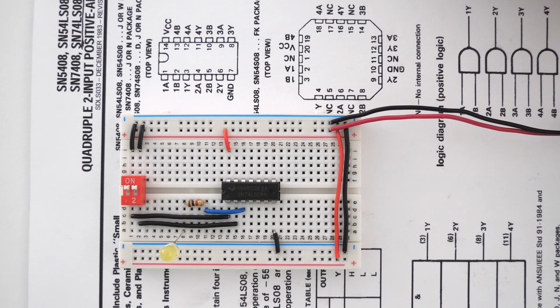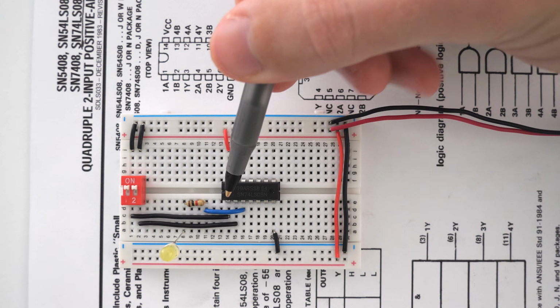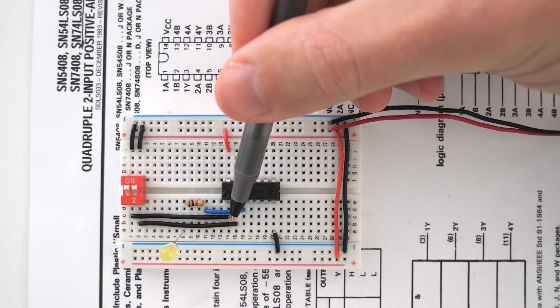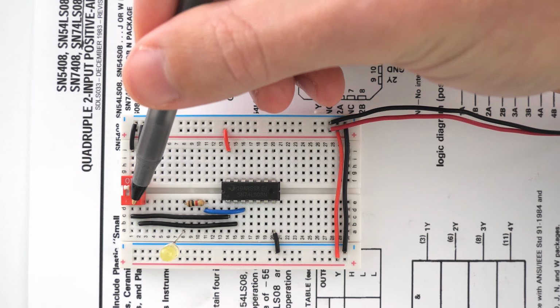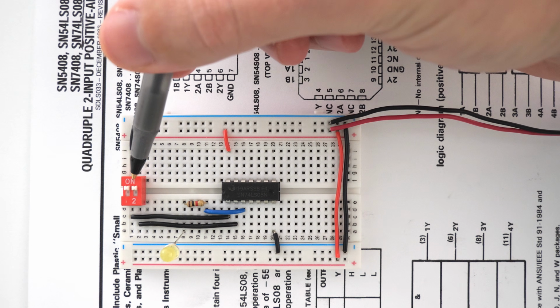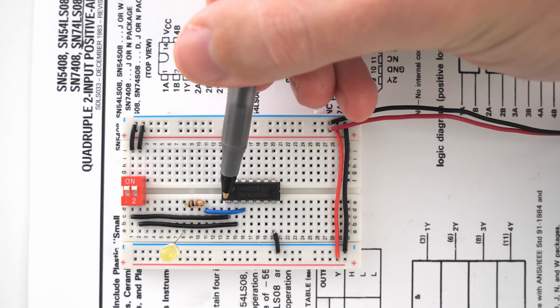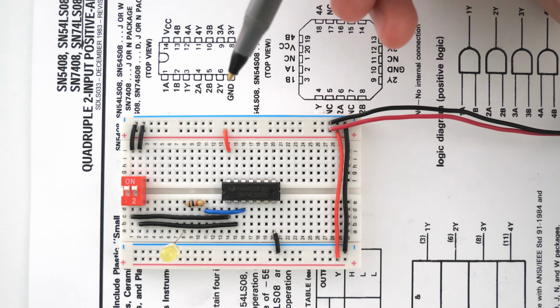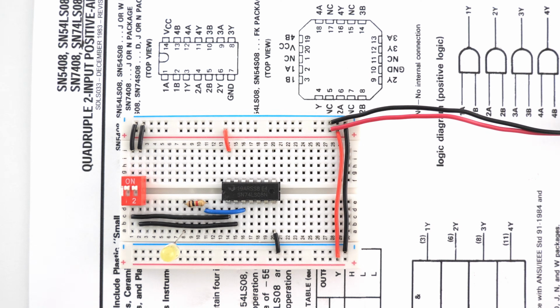which is what we want. And we actually have the inputs wired up a little bit strange. Input A and input B are actually wired by going through this black wire, across the switch, and then into these grounds. Right now, both of them are on, so we actually have both of these wired to ground right now, which is why the circuit is off.